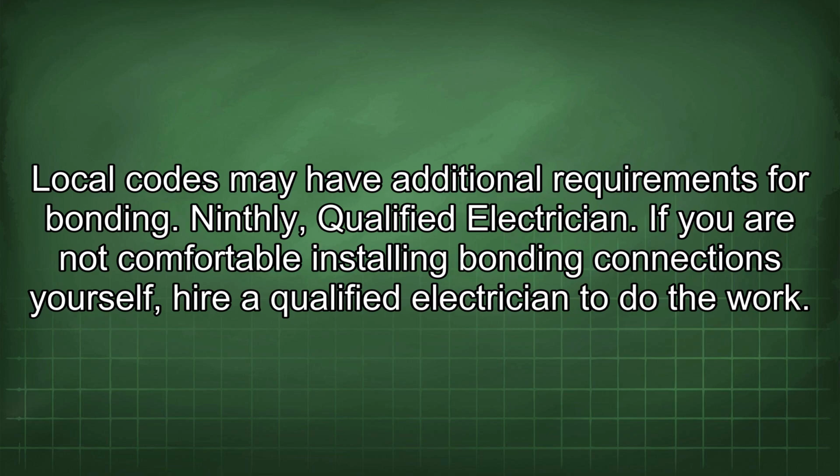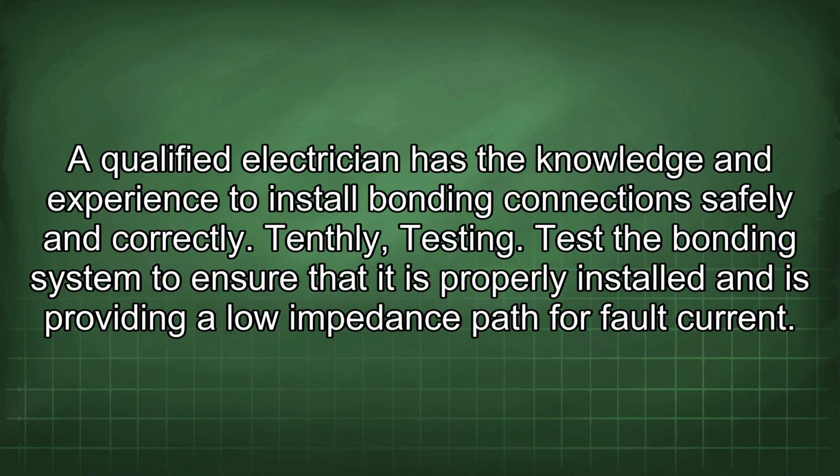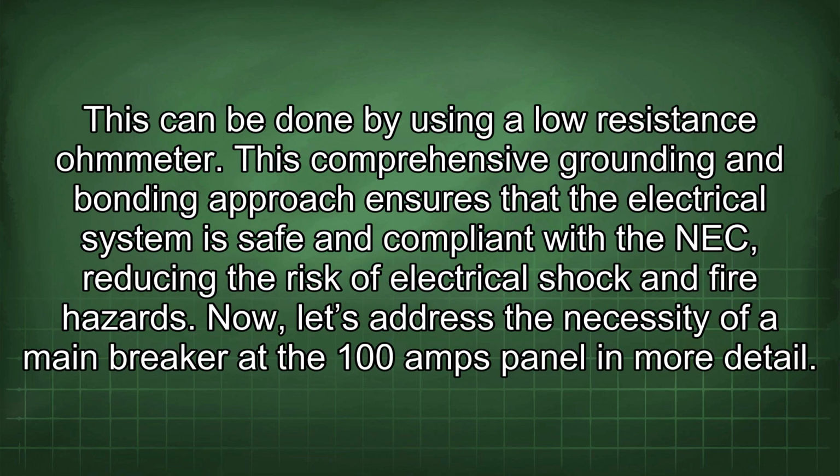Ninthly, qualified electrician. If you are not comfortable installing bonding connections yourself, hire a qualified electrician to do the work. A qualified electrician has the knowledge and experience to install bonding connections safely and correctly. Tenthly, testing. Test the bonding system to ensure that it is properly installed and is providing a low impedance path for fault current. This can be done by using a low resistance ohmmeter.